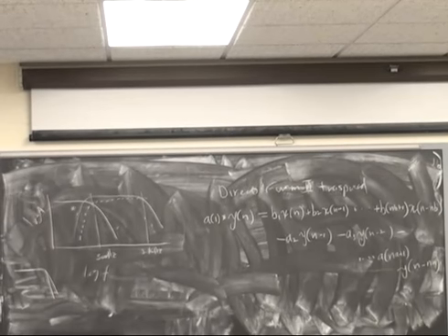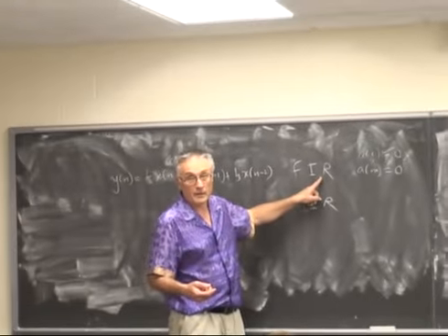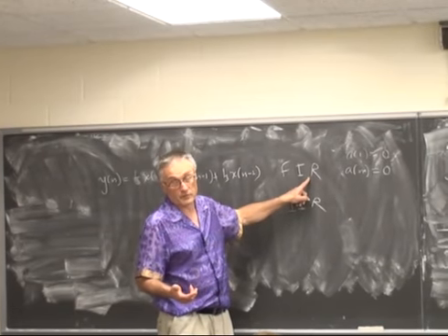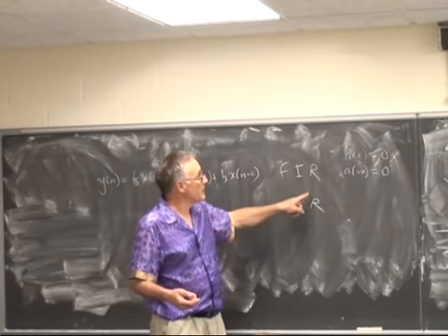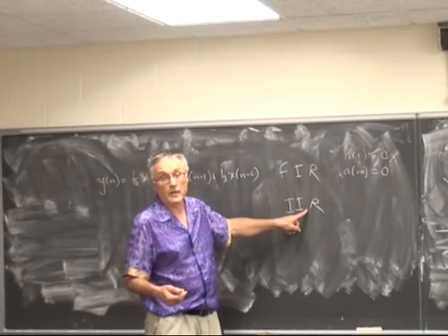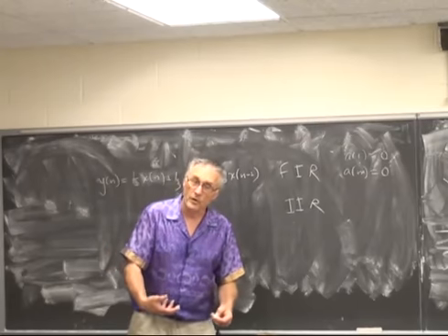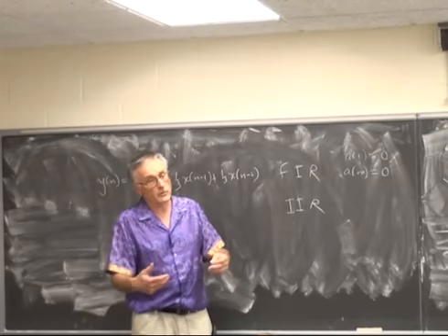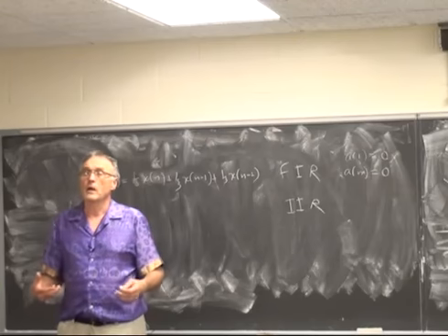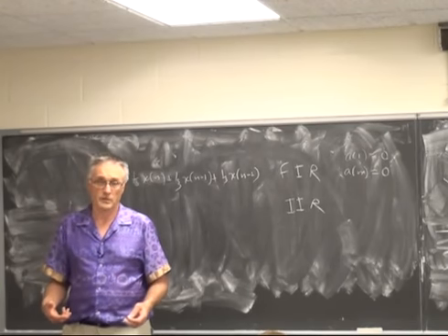And so if you are computation limited, if you don't have some big kick-butt 3 gigahertz machine, but you're trying to use a microcontroller, say, then it makes much more sense to use an infinite impulse response filter and to suffer the increased design difficulty, the more uncontrolled phase shift, in return for a sharper cutoff function with less computation.